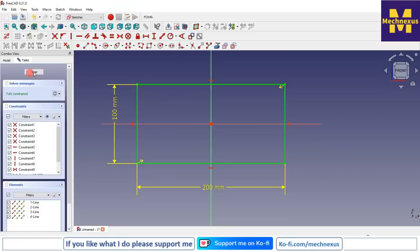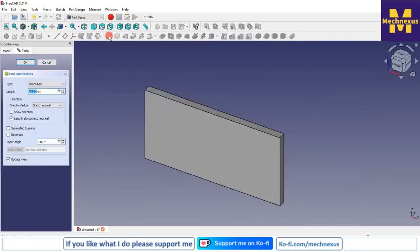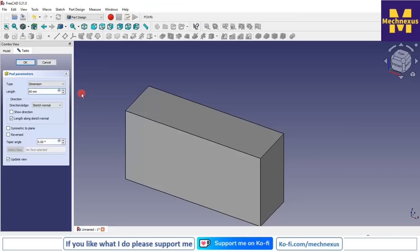Now I will go to the task tab, and here I can see the constraints, and here I can see the entities of my sketch. Now I will close it. Now I will click on the pad. So once I click on the pad, you can see the pad length, so here I can give my length. Let's say I give it 60.